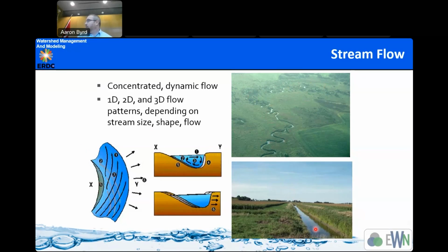As engineers, we really like nice straight rivers. These are channels, but we like them a lot. This is really what we simulate in GSSHA, not this. So that's one of the limitations, right? 1D flows straight down the middle. If you need to look at aquatic habitats within your stream, you need a hydraulics model. We can get you the boundary conditions that get you to where you need to be. So just realize what the limitations are here.